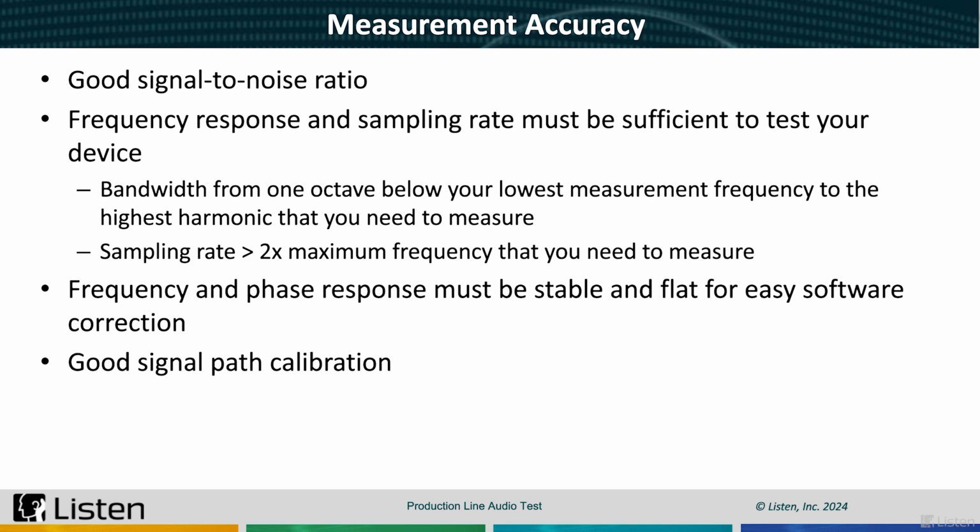In SoundCheck, we do this through the hardware and calibration editors. What's nice about this is that you're calibrating the entire input or output signal path on a system level. This avoids the need to calibrate each device separately, and signal path calibration is quick using the software's self-calibration test sequences. You can store and recall multiple calibration paths for different channels and configurations.